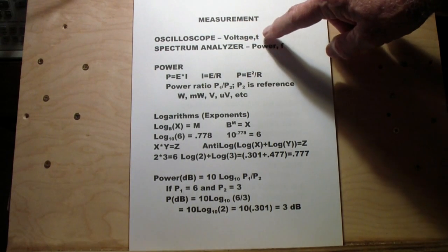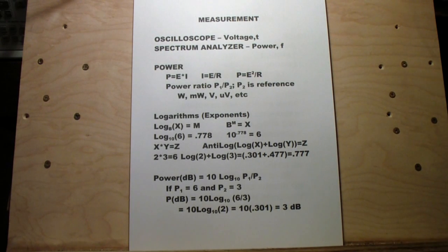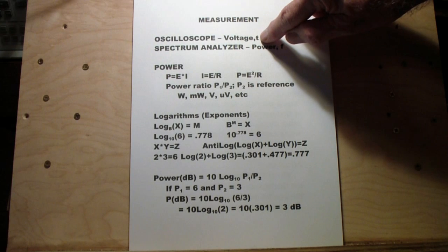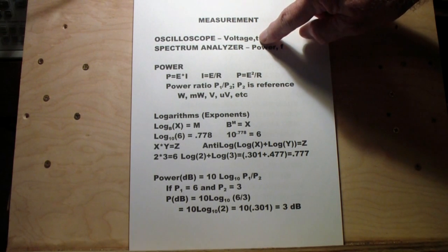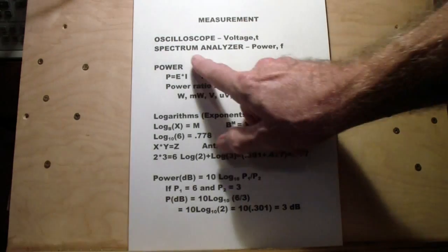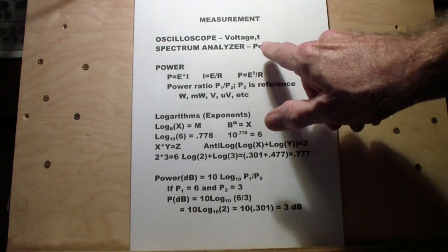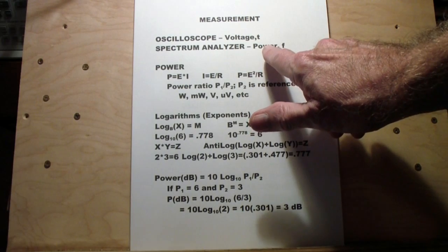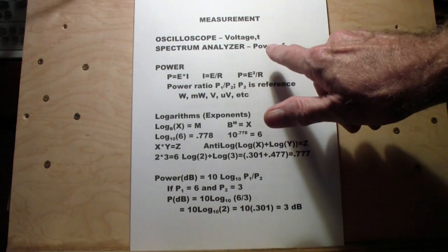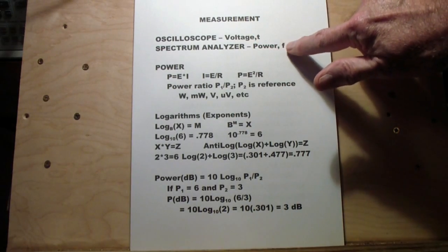You notice that, for example, when you look at a square wave. Now a square wave, as we'll find out later, has a number of frequencies in it. But what an oscilloscope will display is only 1 over the period, in other words, the fundamental frequency. A spectrum analyzer, on the other hand, is much more related to measuring power. Sometimes it's called the power spectrum or the power spectral density, but nonetheless it's the power and the frequency.